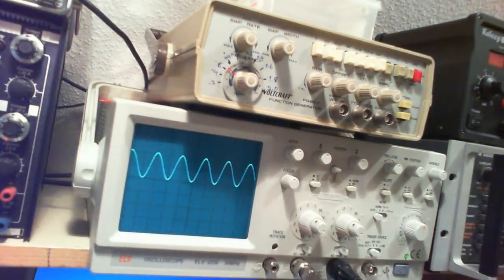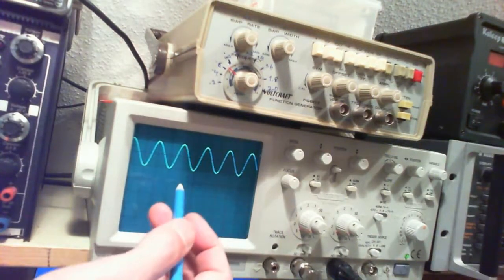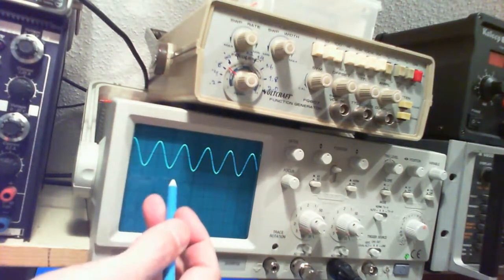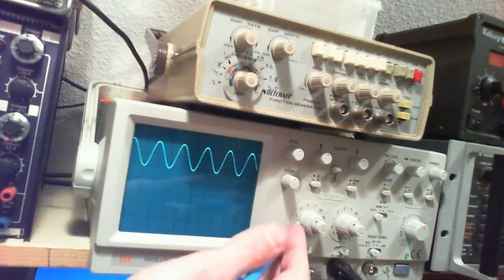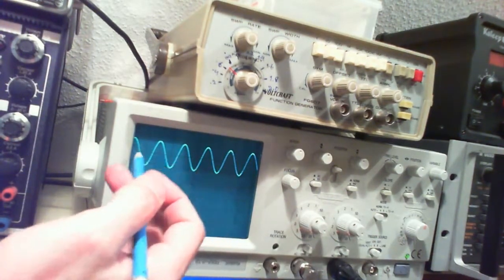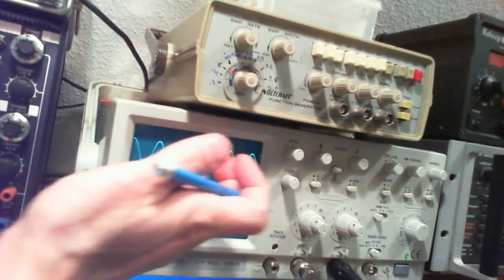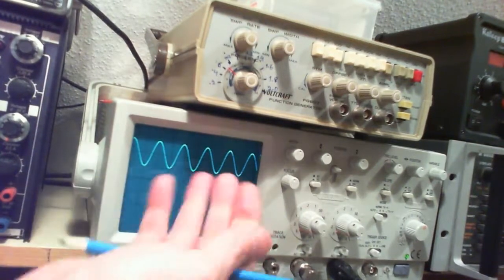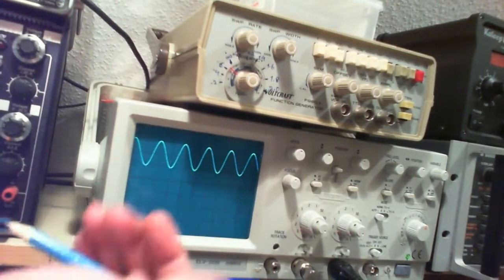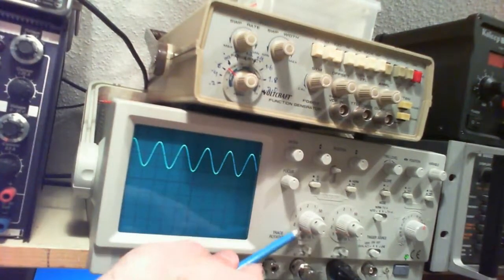So now I have a positive offset of, for example, 10 volts, because this is 5 volts per division, and now the line has moved over here, and this signal is centered about this line, which is in the center of the signal. So that's 2 vertical units, 2 times 5 is equal to 10.